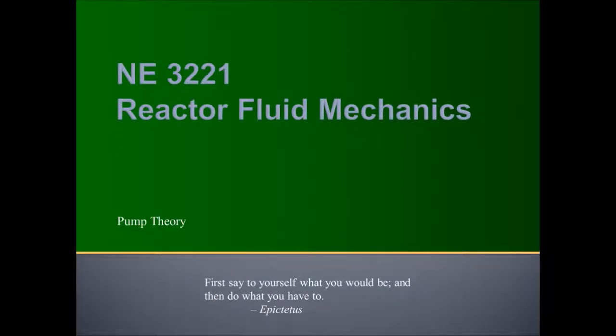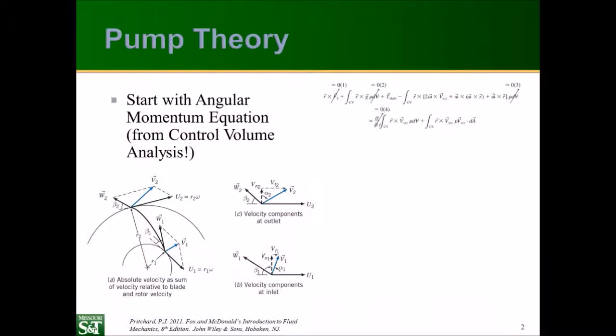Welcome to this discussion of pump theory for reactor fluid mechanics. We're going to start with the angular momentum equation from our control volume analysis section at the beginning of the class. The basic idea here is that we apply a torque to the pump, and that applies a force to change the angular momentum and the kinetic energy of the fluid.